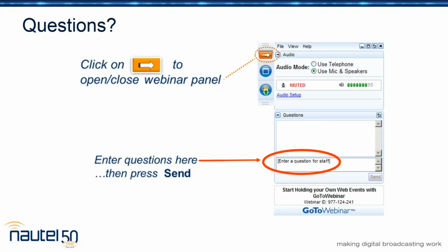Then you'd set it so if the modulation drops to a certain level for 5 or 10 seconds, you would switch to the stream preset, and then you would start streaming. The thing that would be important is to set up an automatic email notification that it did switch, so that you know to check whether or not the primary STL is back. And if it is, log into the AUI and switch it back. Correct. Okay, very good. Thank you.